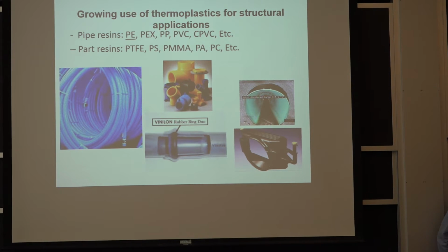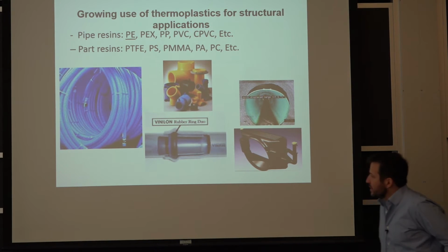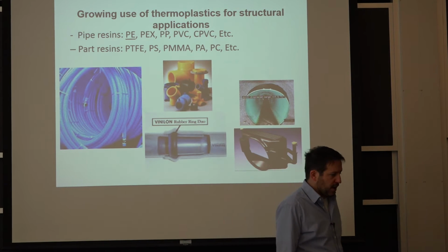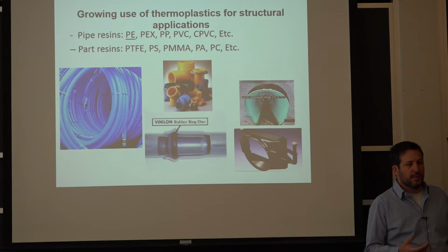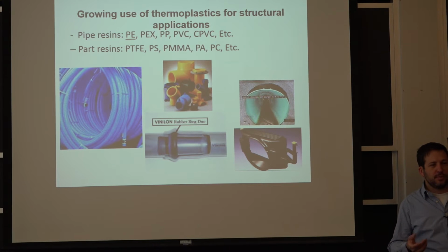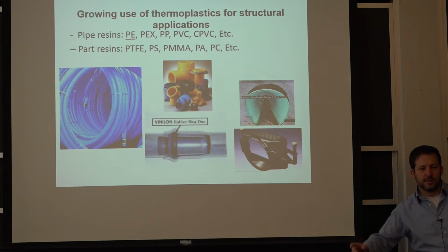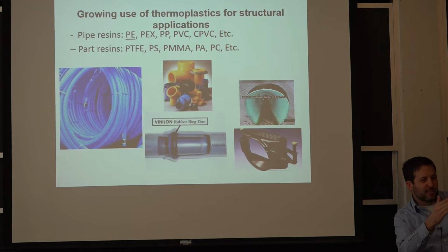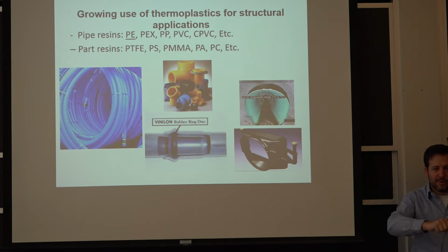And the reason, when you're looking at these coils, and this is a big one, but you can have much smaller ones, is you have fewer connections. So you can come with this roll of tubing and you drill some holes through the walls and you go kind of around the house without having to cut to a precise slant, put an elbow and solder all that. So it's very, very quick installation. You only need a connection when you're getting to the faucet or